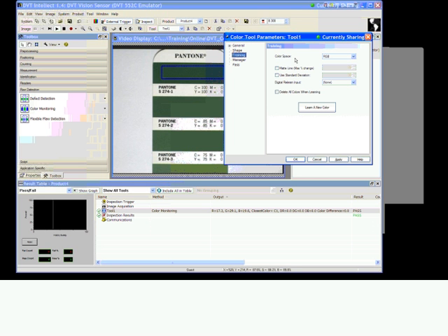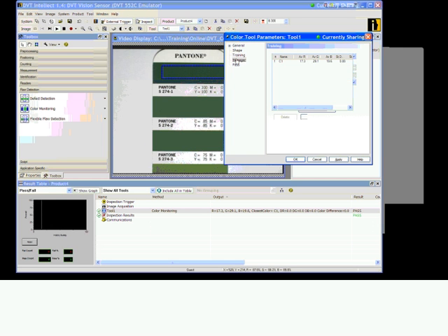Changing the standard deviation is a way to differentiate, or not differentiate, between parts that are very smooth versus parts that are porous and not very smooth. That's because the standard deviation within a part that's not very smooth is going to be a little larger because of all the different changes in the surface, basically the way the lighting is reflected because the surface is not smooth. So you can change that.